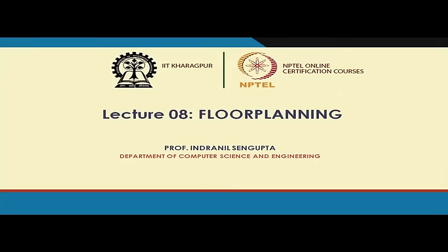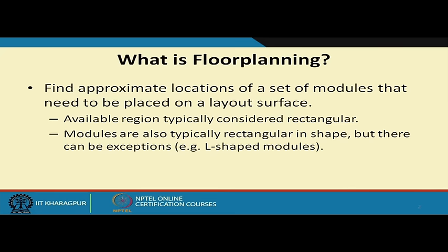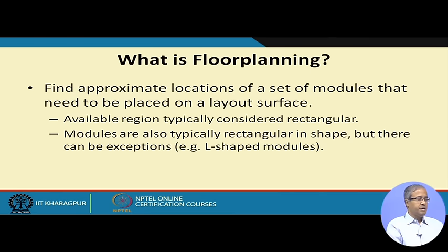So, we consider now the next sub problem, namely floor planning. Let us first see what this problem is all about. Now, in typical VLSI physical design, what are we trying to do? We have our playground, which is the silicon floor, where we have to lay out all the circuit components. Floor planning means, just to recall the analogy I gave earlier, it is like building the plan of a house.